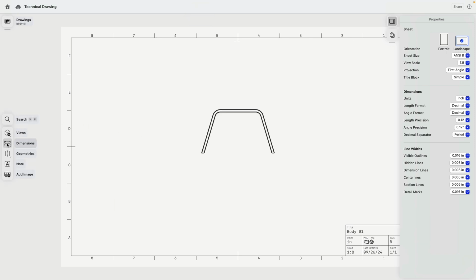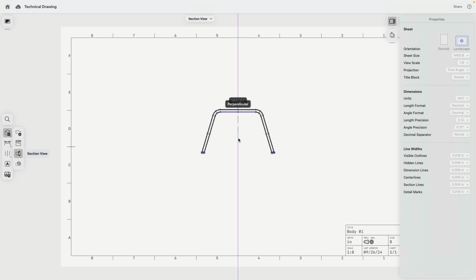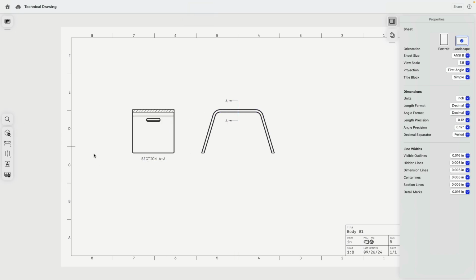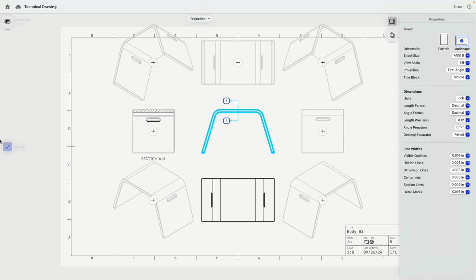Then actually I can create a section view. Let's say from there to there. Bring this over. Perfect. Can we actually create a section view from that? No, we can't because that is already a projected view. So if I would like to have that other projected view, then from this, I might need to create, I think, a projection. So there we can go down.